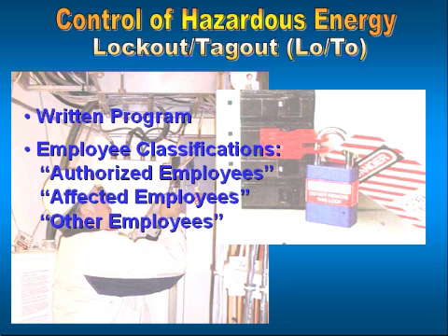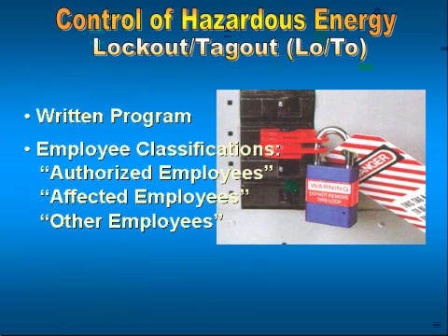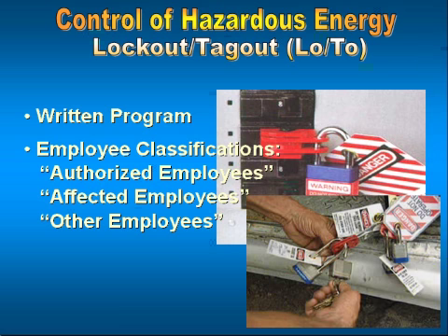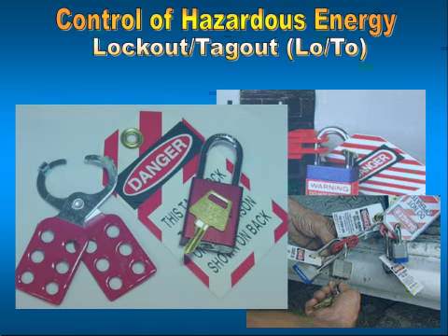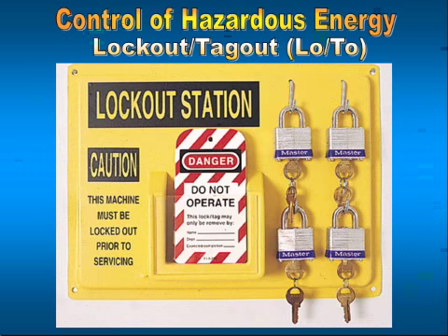The other employees, as referred to in the standards, would be someone from outside your company, someone from downtown who's brought in on a contract. They bring with them the use of their tags and their locks and their procedures from the companies that they work for. They may be different than what we have out there, although the basic premises will be the same. But the idea here is awareness. We want them taught and become aware of what our tags mean, just like we need to become aware of what their tags and their lock colors mean, so that it's a free flow of information and it better protects all that are exposed.